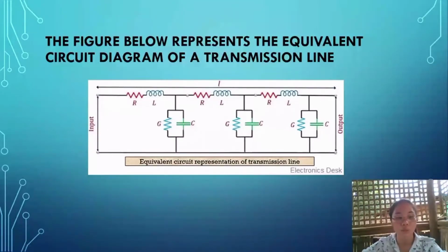The two conducting wires, due to separation, hold some capacitance, the C, but the dielectric medium does not provide complete insulation. Hence there is some leakage, a leakage current that flows through it. Telephone lines and electricity supply lines are some examples of transmission lines.